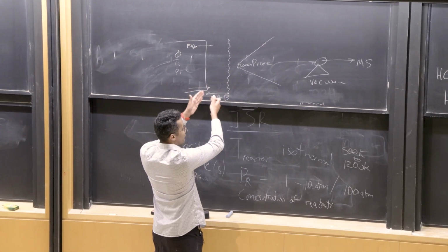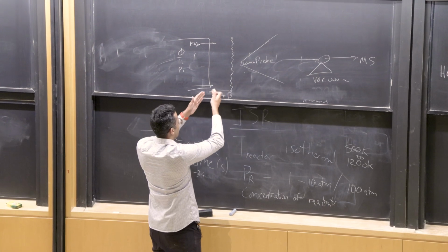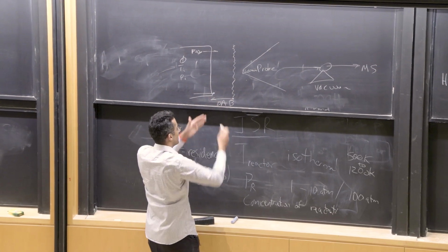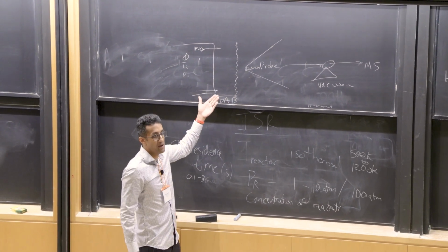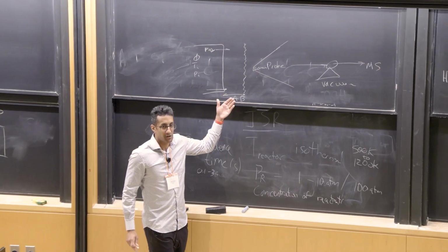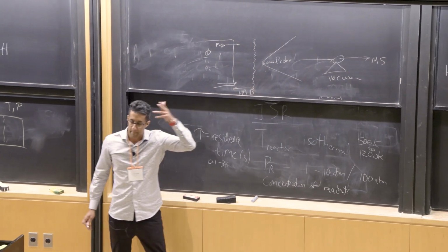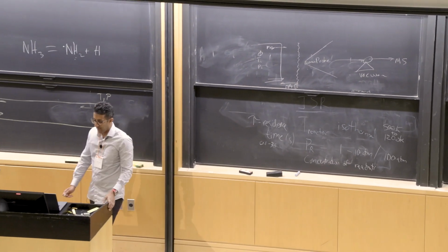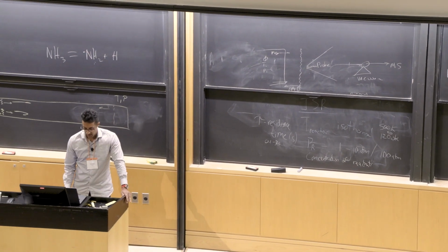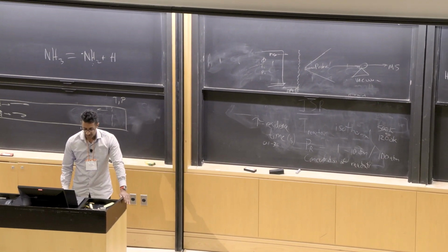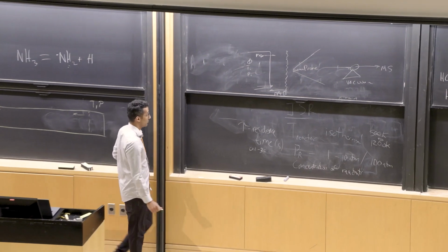Your resolution might be like 500 micron. If your flame sits 1 millimeter away from the surface, you might only get 2 measurement points or something. So because of the physical barriers or the obstruction of this cone, this quartz device that's doing the sampling, you prefer to do it at low pressure.